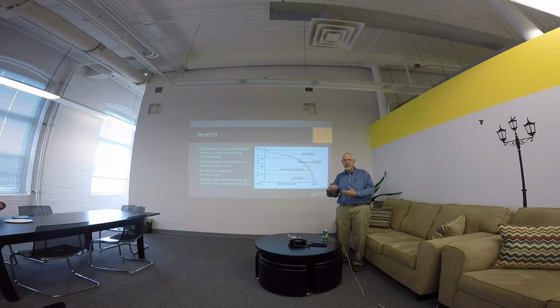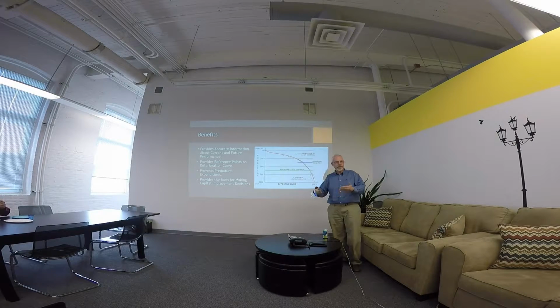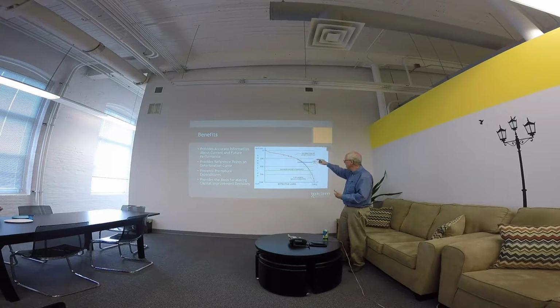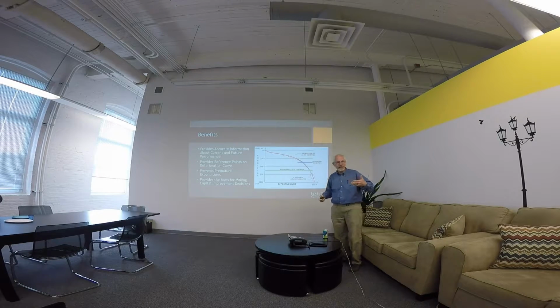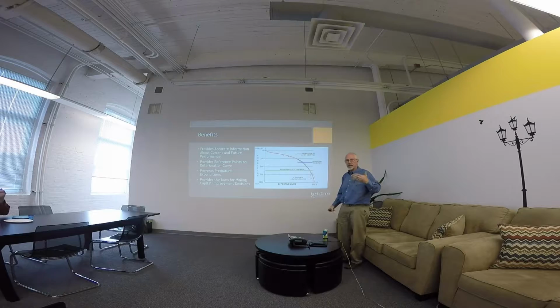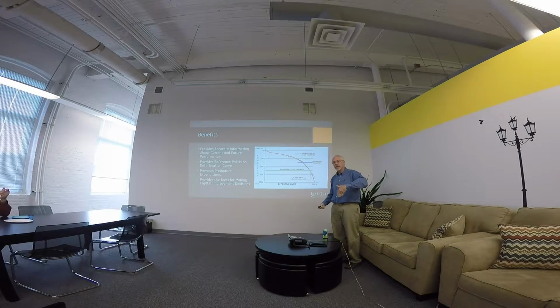And it wasn't until they did borings of the road that they found out that the contractor on that ramp used subsurface material for the road, causing it to deteriorate quicker. So taking those points of your different assets and having a good standard condition assessment allows you to look at its deterioration curve compared to what it should be, and then you can make expectations. They knew with that on-ramp to replace one of the on-ramps before the other one, so they were able to start looking at some of their capital investments.